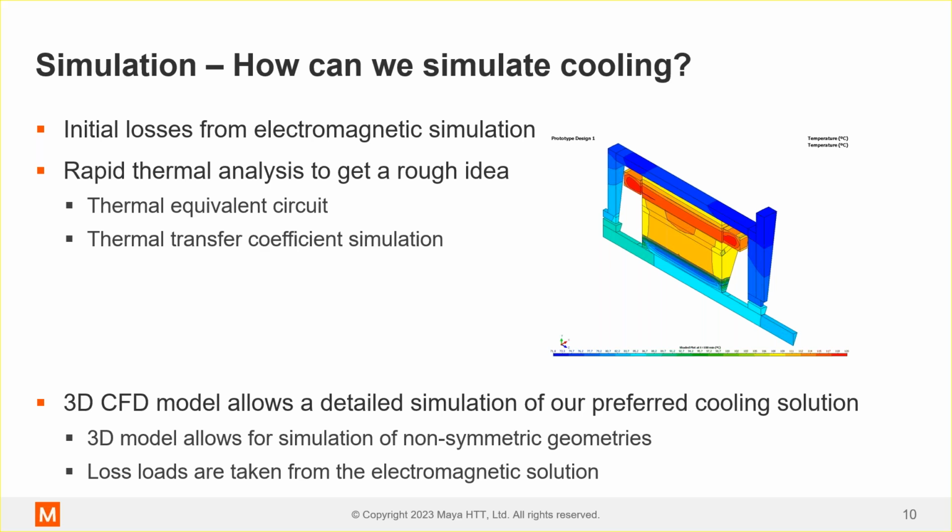The most detailed way, of course, is to run a CFD analysis. This gives us a lot of freedom to play with cooling solutions. It gives us a lot of accuracy, results that we can be very, very confident in. But these can be complex to set up. They can take time to run. And often we try and avoid doing too many CFD analyses if we're trying to get through a project fairly efficiently.